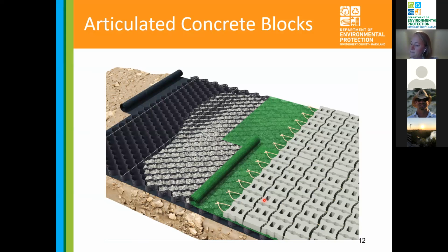And then the black cells themselves, I saw a question about the material. Those are going to be made of plastic, high density polyethylene, I believe. And that'll be also structurally rated just like the access road. And then there's a hardware cloth mesh layer above that before you get to the concrete. And we chose concrete because it's been tested thoroughly.